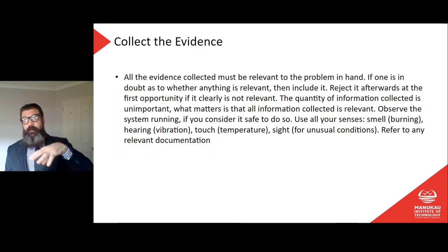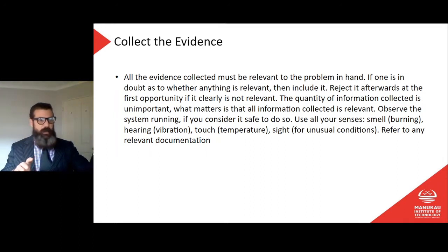So I've got to think a little bit outside the box here, because my first thought is power to the switchboard, yes. Power in the switchboard, yes, everything's turned on. Okay, well then I should have power at my pump. No. I should have power at my card reader. No. But I've got power on the circuits that go out. Hang on, what's going on? Emergency stop is a safe bet in that scenario. There's another control circuit that is affecting or controlling those things, right?